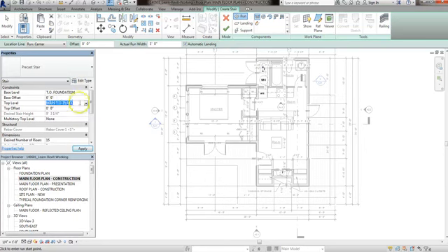Now we want to do the main top of plate, right? But as we know, this deck level is already set 3 inches below that, and the last step is actually going to be the step from the stairs onto this deck. And steps are normally about 7 inches. So 3 plus 7 equals 10 inches. So now, oops, and not main top of plate, make sure it's main top of subfloor. Now we have 3 risers.